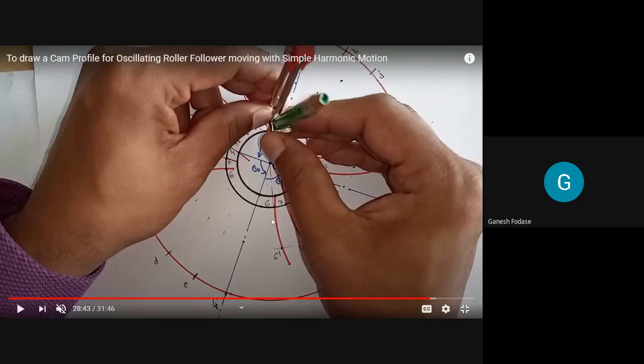As the follower is roller follower, I told you what actually 1 dash, 2 dash, 3 dash, 4 dash, 5 dash, 6 dash is. These are nothing but roller centers. So with these points as 1 dash to 12 dash as roller centers, draw rollers. As procedure for roller follower is discussed, draw rollers and then draw a smooth curve passing through base of these rollers. So try to draw roller circles with radius equal to 7 mm, which is known to you. It's given to you. With radius equal to roller radius and centers at 1 dash to 12 dash, draw roller circles passing through these points 1 dash to 12 dash.